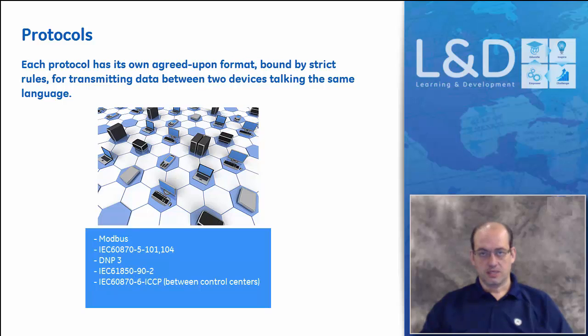Okay, so we talked about communication, we talked about communication architecture. Once the communication has been decided, the layout of communication, the physical communication, there comes the big question of what protocol to be used between all the computers that are laid out in a SCADA system. Computers could be front-end processors or remote terminal units that are sitting in a substation, and would communicate to the mainframe or the central management system using any of the common protocols.